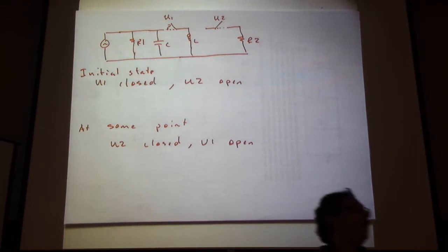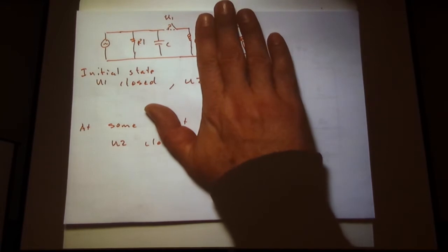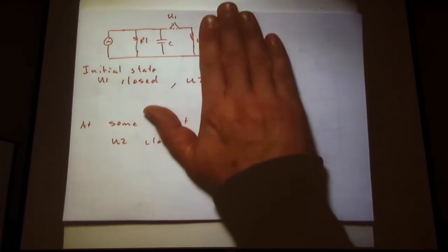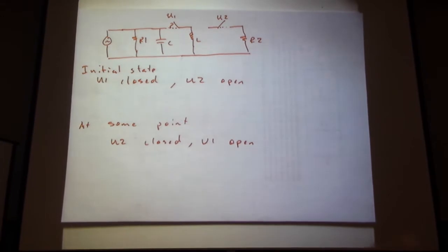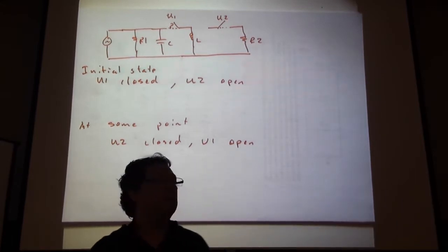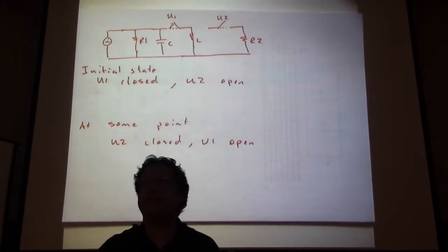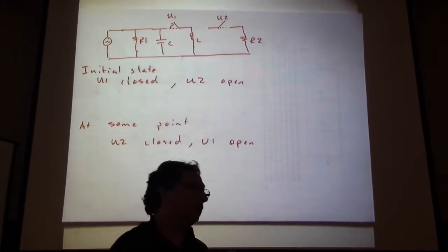If we drive the left part of the circuit to DC steady state, we have current through the inductor. If we leave this open and open that switch, what happens? Well, that inductor is still trying to force so many amps through it. That's the bad thing. Depending on the size of the inductor, if it's a big inductor, you'll get serious arcing.